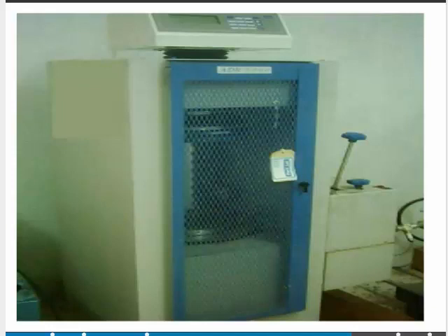So minimum 3 specimens should be tested at each selected age. If the strength of any specimen varies by more than 15% of average strength, results of such specimen should be rejected. The average of 3 specimens gives the crushing strength of concrete, and how are we calculating that compressive strength?